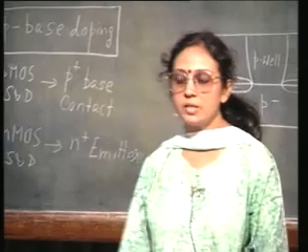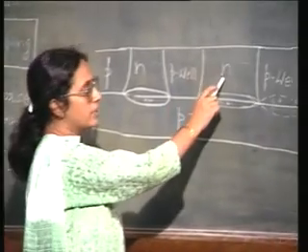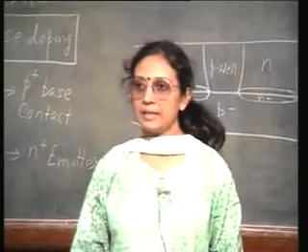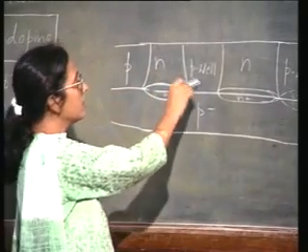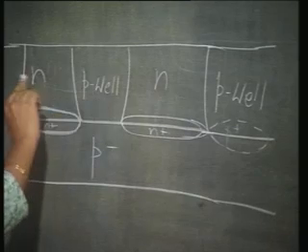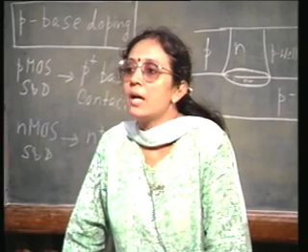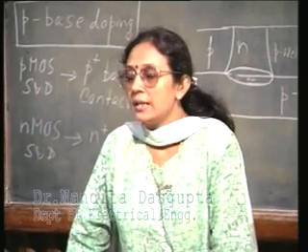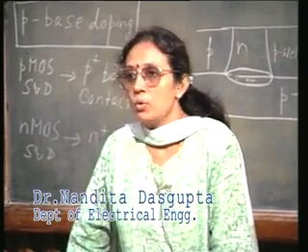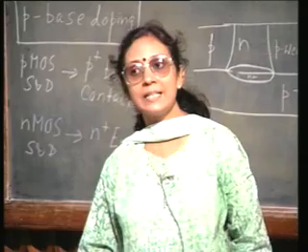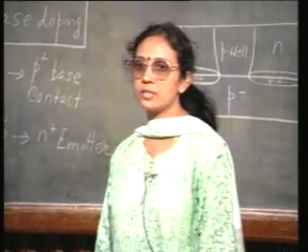And the other possibility is, instead of this N epitaxial region, you could have a nearly intrinsic epitaxial region. You see this one is basically a POL technology. We have realized an N epitaxial layer, and in that we have put in the POLs. Now, instead of doing that, we could have a nearly intrinsic epi layer and then go for a twin tub technology, that is we realize both N wells and P wells, so that the packing density of the bipolar junction transistor is increased.